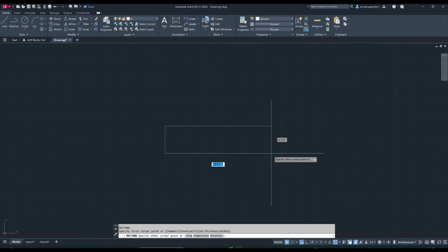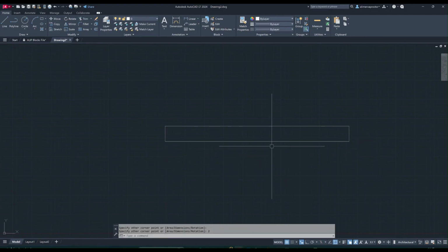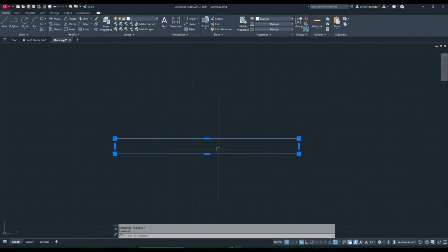We're just gonna type 24 and then press TAB on your keyboard, above the caps lock, and 3, enter. So we should actually have this rectangular box. To check the measurements, we go up to measure here, do quick, and make sure it's 2 feet by 3 inches.